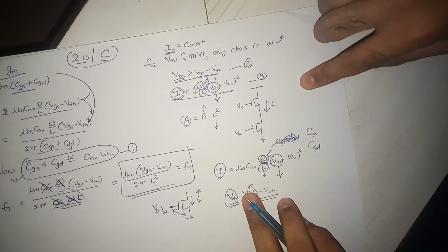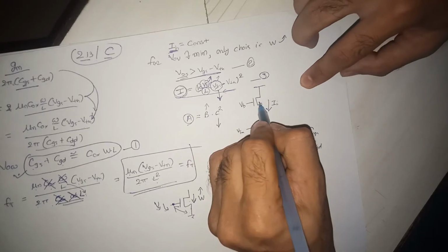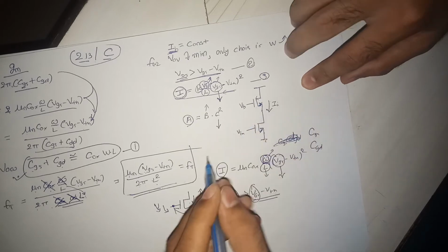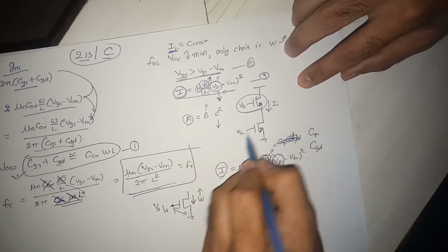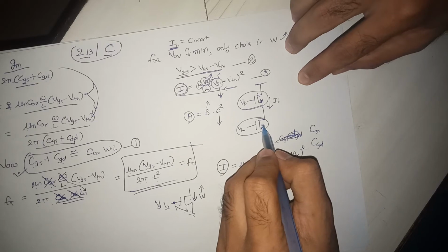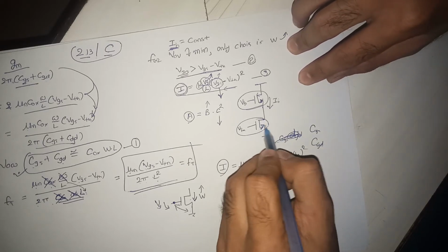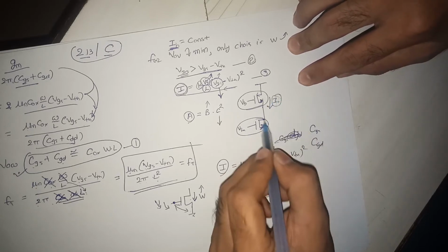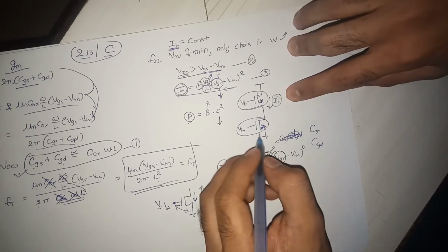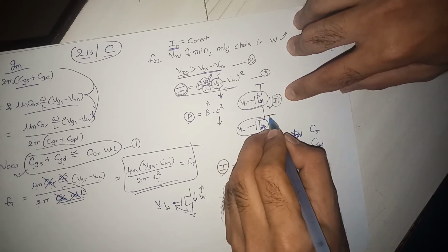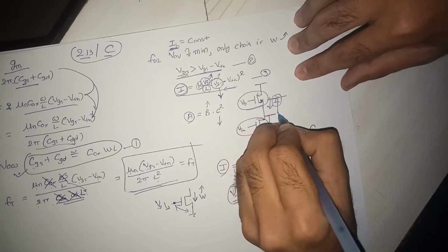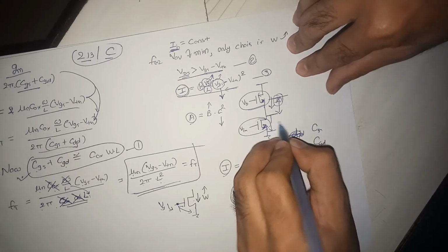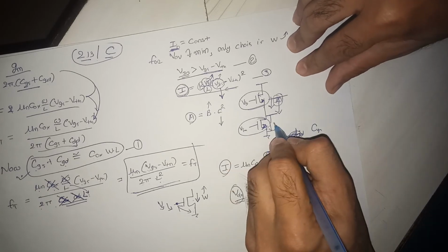So this is actually a practical situation where you need to consider this. This is NMOS and this is PMOS. Let's say you have the bias PMOS and input NMOS. What I meant, the amplification device will be NMOS here. If you want the same I, your power budget is limited and you want higher headroom, ultimately what I'm trying to tell is the minimum requirement of overdrive voltage will be less.